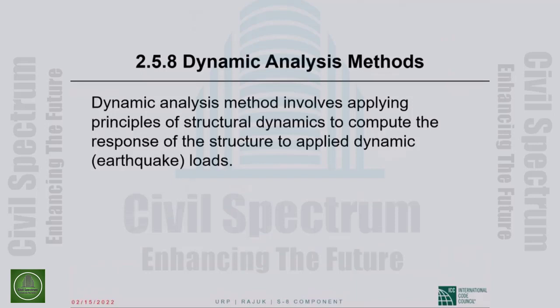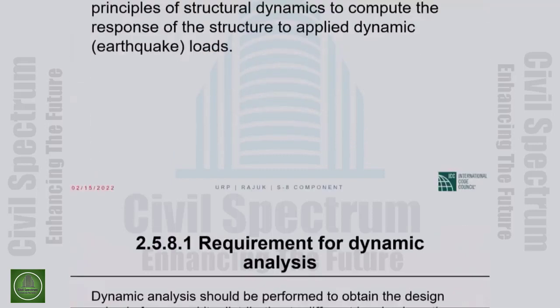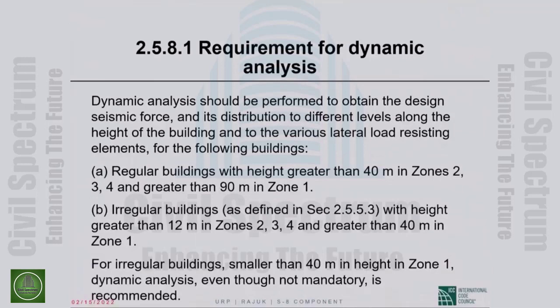Then further on, 2.5.8 of BNBC 2020 says, under dynamic analysis methods, dynamic analysis method involves applying principles of structural dynamics to compute the response of the structure to applied dynamic or earthquake loads. That is just a description, if you like. So the earlier slide said equivalent lateral force procedure can be used only under certain conditions. This section 2.5.8.1 gives us requirements for dynamic analysis.